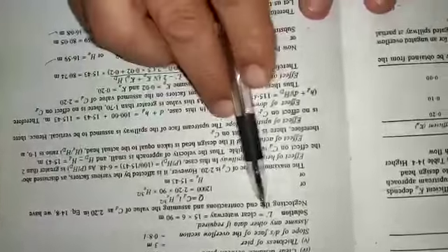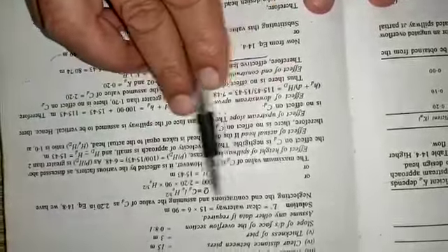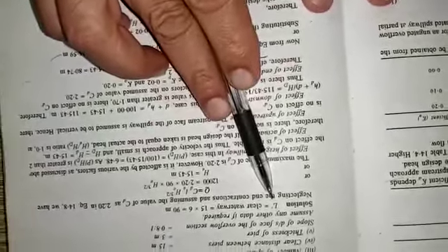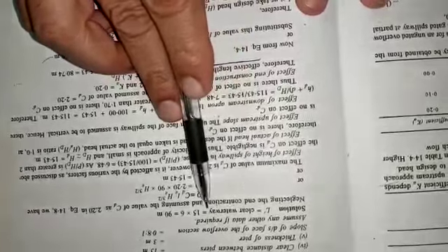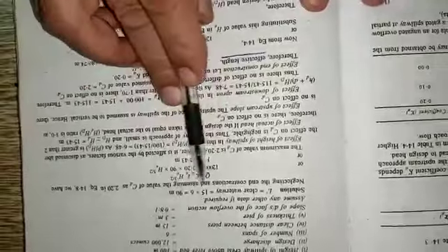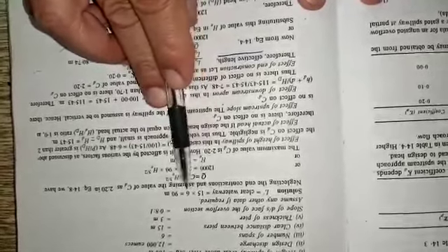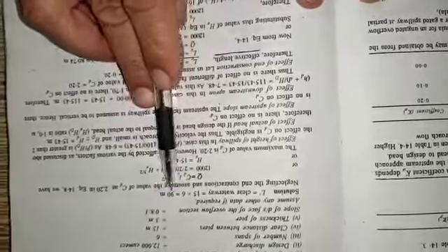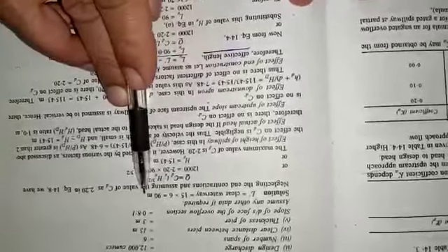This is the data given. Now, from this data, we can obtain, as we have discussed in the earlier numerical example, the L dash, that is the length of the spillway, which will be equal to the length of each span into the number of spans, which comes out to be 90 meters.